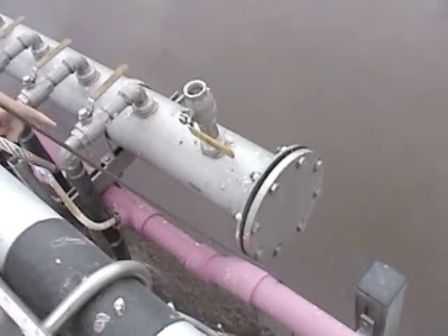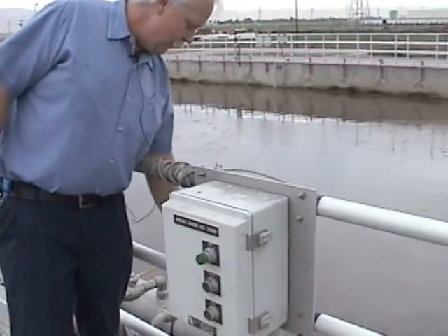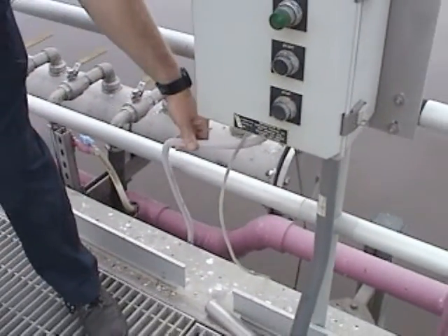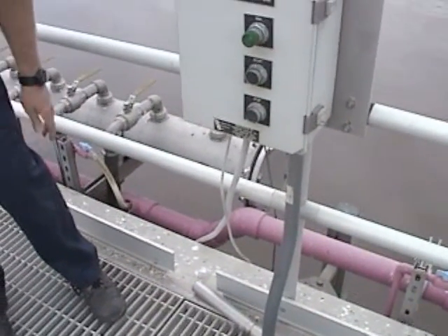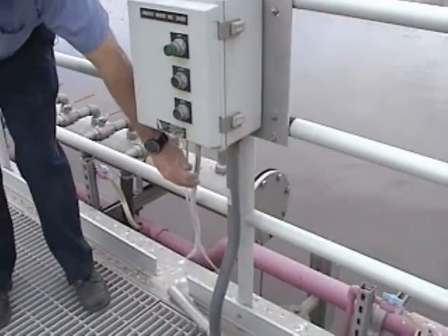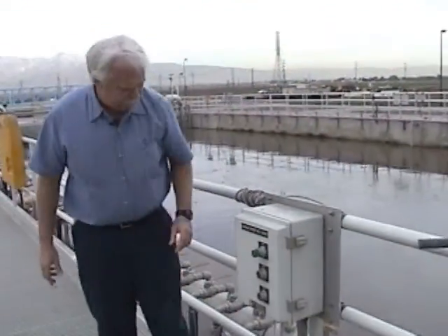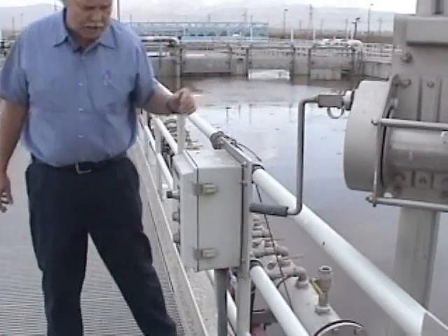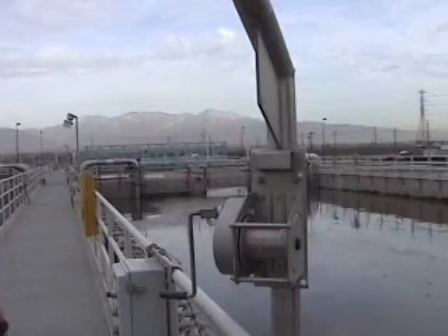It's important on this system to remember that there are about 7 different alarms coming through to the SCADA system through this cable right here. So in addition to providing power to the anoxic mixer, the cable also carries a lot of telemetry, and it's kind of delicate. When you're pulling an anoxic mixer out, remember that in addition to this power cable, which is pretty tough, you have a data cable coming up, and that's not so sturdy. So you would just latch this onto the hoist and then winch it up. Then each one of the anoxic mixers has a cylinder like that where you can relocate the hoist to.